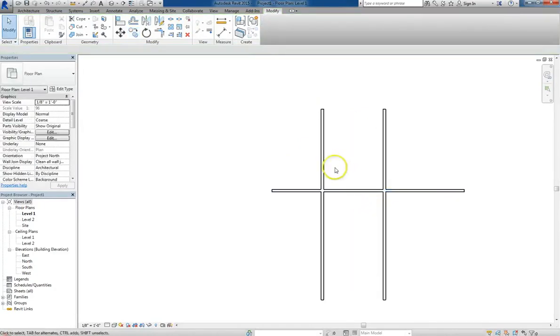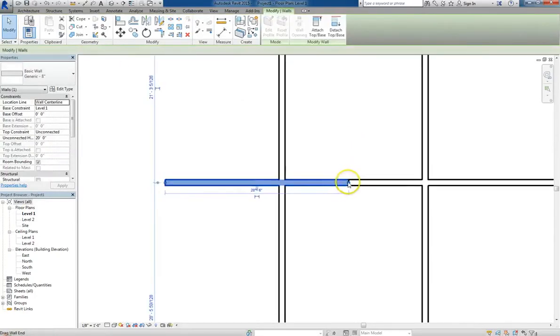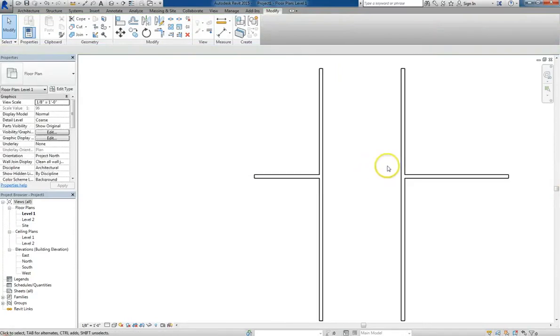So now if I want to trim it out, put a hole in the middle wall section, there's a bunch of ways we can do that. So if we want to do that, we can either split the element or split it with gap. I'm going to split the element this time. That's the keyboard shortcut SL. And when we click in there, you'll notice a little line appears. That's the point from which your element will split, and you can move it over to create a gap.